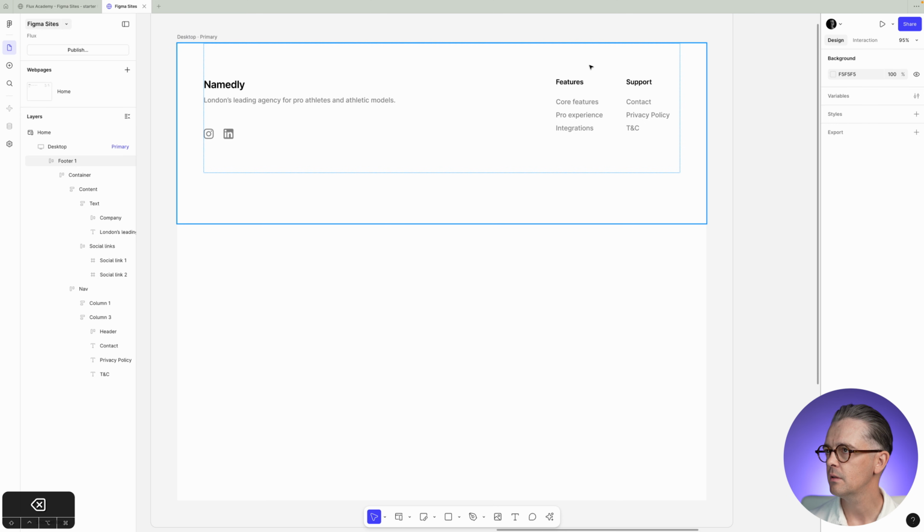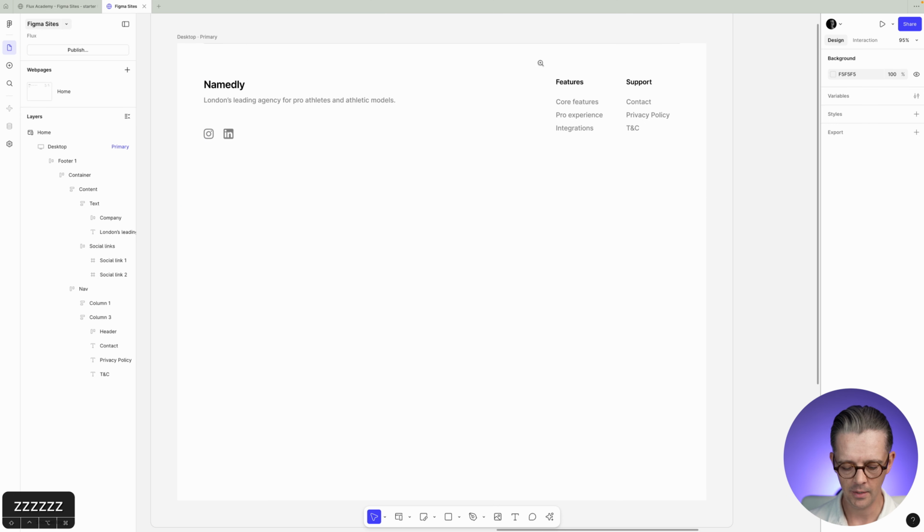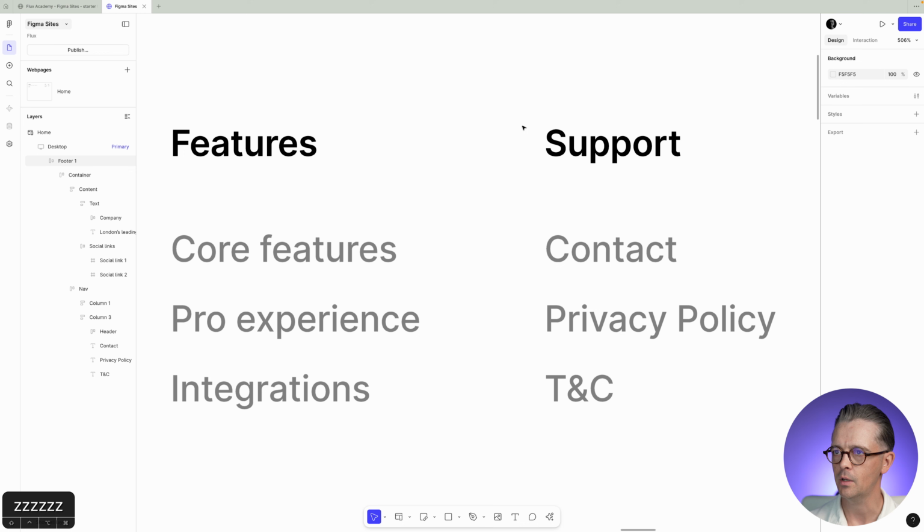So for this features category, and I'm going to zoom in, and another way we can do this is if we hold down the Z key. You can see that I'm doing that from the bottom left shortcut menu, and it's giving me this magnification icon. If I hold my mouse button down and drag, it gives me this rectangle that I can make any size I want. And when I let go of that, it will zoom to that level. When I let go of the mouse button, there we go.